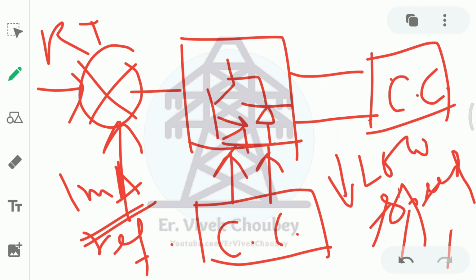So the compressor keeps on rotating at a very low speed, and whenever the speed is required to be raised, what happens? The speed rises up, but it does not attract that much amount of current as like a non-inverter AC, where the current reaches 5 to 6 ampere. Here it reaches somewhere between 2 to 4 amperes, okay, or 2 to 3 amperes, something like that. So there is almost 50% reduction in the current that is taken by the induction motor. And because this current is doing nothing but just starting the induction motor in a non-inverter AC.